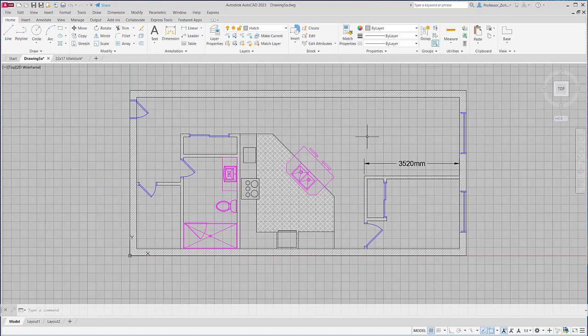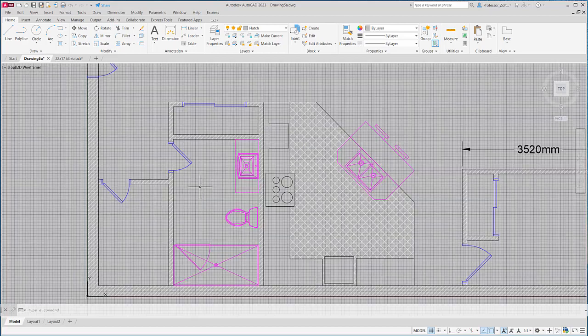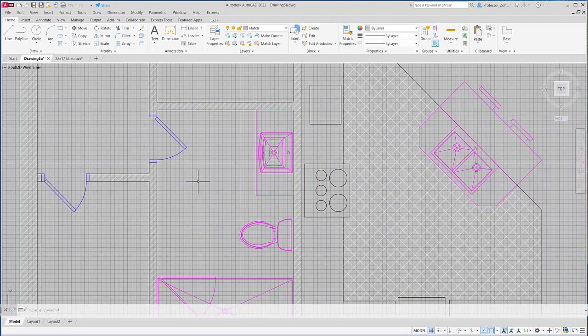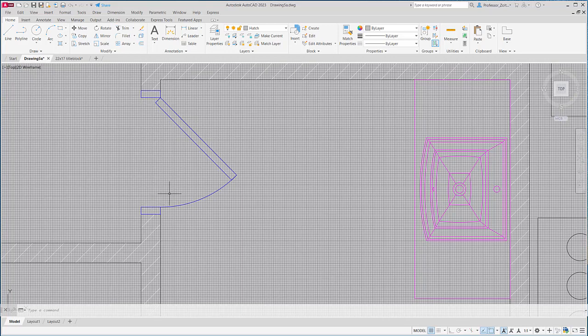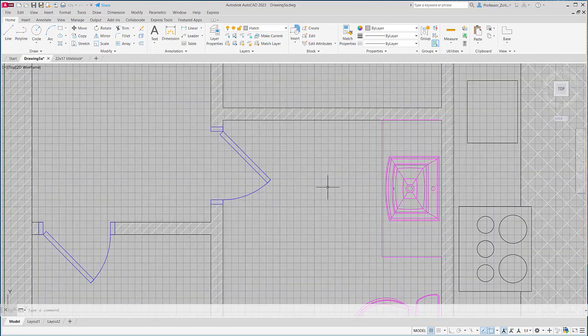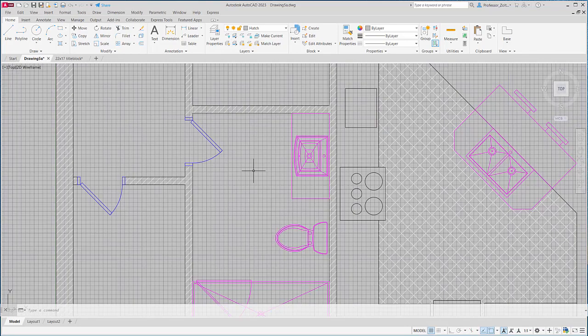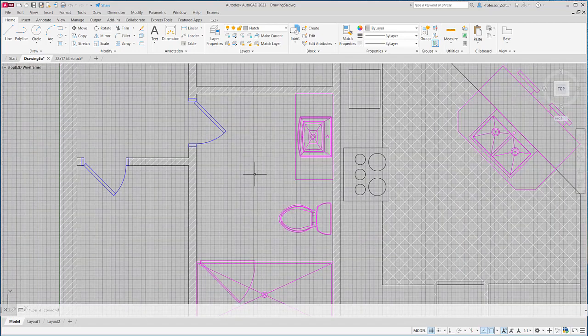If you have any other areas that you want hatched, let's say the kitchen or the bathroom area, by all means. Now this is a bit tricky only in the sense of this. You'll notice that this floor pattern, or wherever the floor is going to be, has to end somewhere inside this doorway. But I don't have a line for that. A couple ways I can do this. Again, I'm trying to show you as many varieties of editing methods that can be used for something like this, and then you can pick whatever's the easiest one for you. I can temporarily draw a line to make sure that that pattern goes to precisely that location. What else can I do?